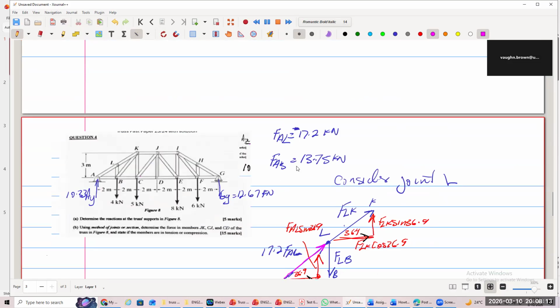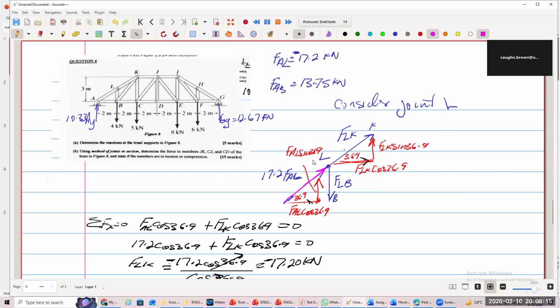So what I did now, moving forward, don't get confused. So joint L now, I change it. I put it going into the joint and put it as positive, because it is in the opposite. Remember the notes tell us when you see it going in one direction, it's minus, it means it's going in the other direction. And if you put it in the other direction, you better change the sign. If you don't change the sign, then the whole problem is going to be off. So remember that. You hear?